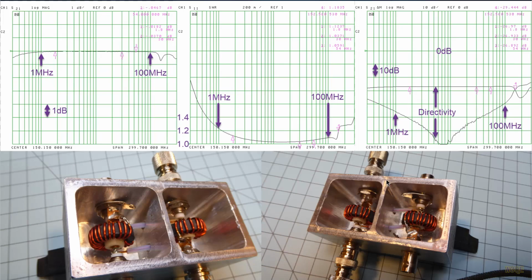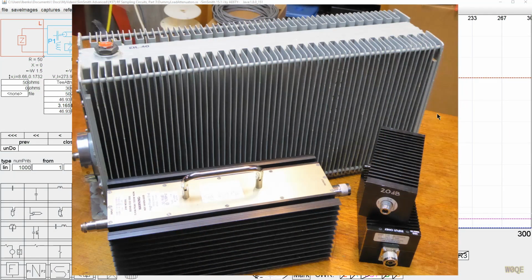And that brings me to the final point here. Another type of RF sampler that I have not mentioned in this video so far is the high-power attenuator. Four high-power attenuators are shown in this picture. These two are 100-watt ones. This is a 200 or 300-watt one, and this is a 2,000-watt one that's oil-filled. If we notice a couple of things about these attenuators, all of them are marked with an input.